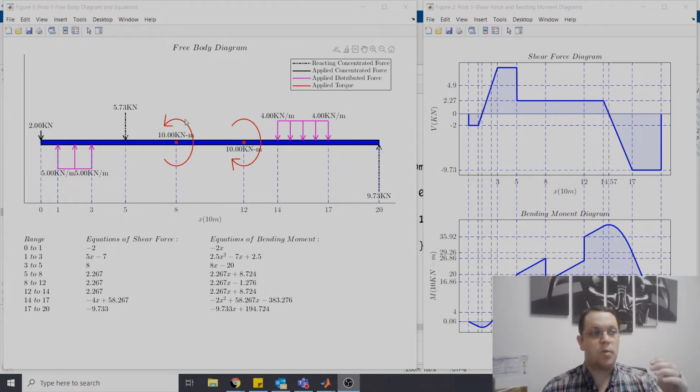And that way you're going to see what happens when you vary where the beam is supported. So maybe you support it at 8 and 12 meters instead of 0 and 20. Or I guess this one instead of 5 and 20, sorry. Because 5, these dashed lines specifically, are where our supports are. So the total loading at each support also gets calculated for you. So very, very handy process overall in order to get the things that are needed to understand what's going on.